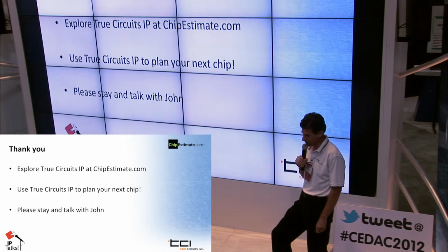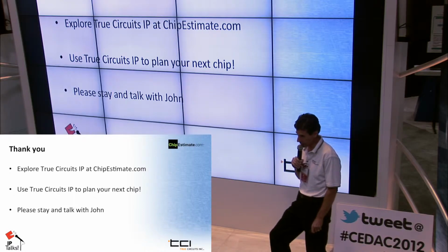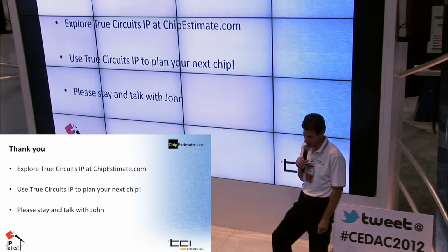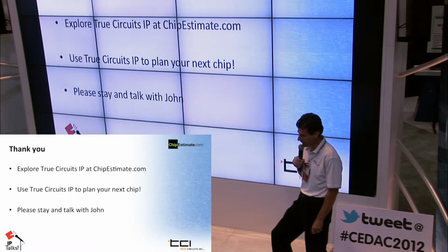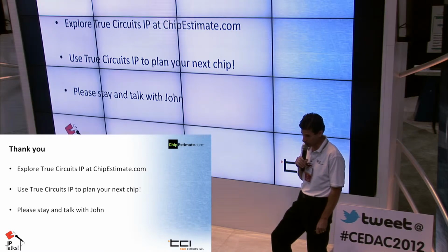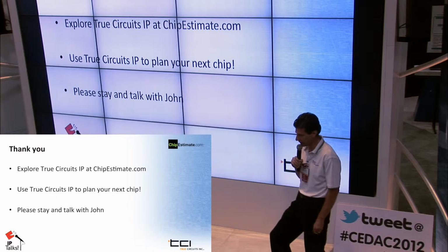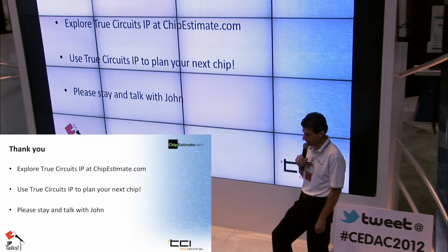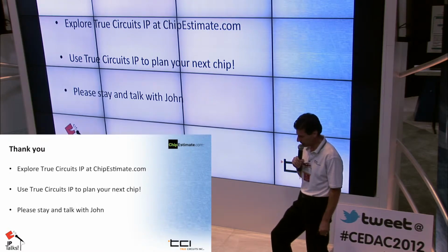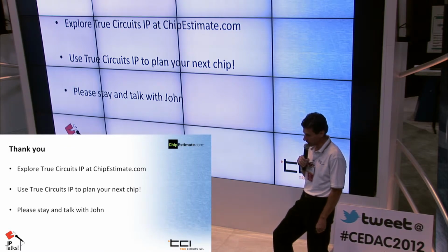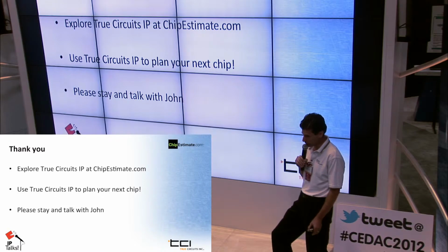So the more jitter there is, the more setup time margin you need, and therefore the lower speed your design will be able to run at. But jitter can also impact timing interfaces through both setup and hold time, depending on the nature of the interface, and reduce the eye opening, things like that. So jitter is definitely a key parameter and one that you should definitely look at.